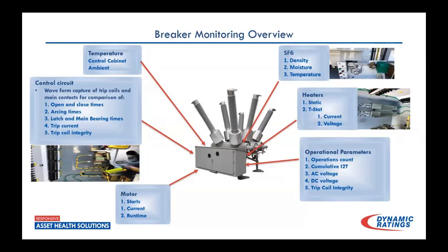So that's the reason for this first trip type of thinking, because once you operate that breaker and it's cycled, now you've remixed those components, and that next test is going to look pretty good. And you'll see in some of the examples from the offline testing I have that you can see first trips at 400 milliseconds that fall within nameplate after the second trip. So if the only testing you're doing is these offline timing and travel tests, which are vital and have their place, by no means disparaging that, you're missing a lot of the data concerning how that breaker is going to operate.